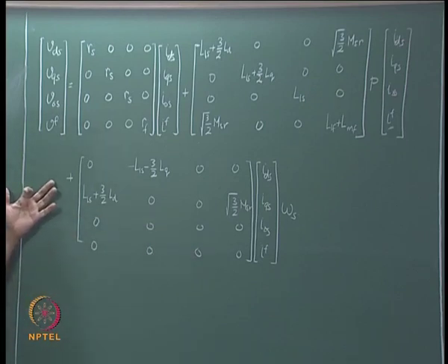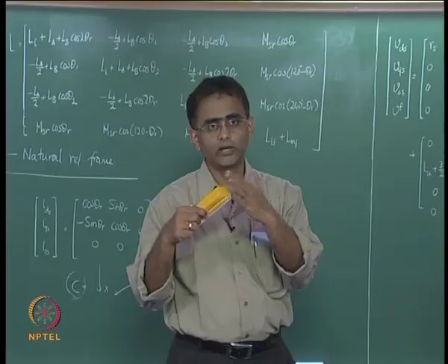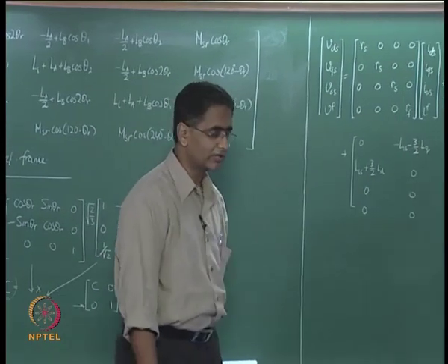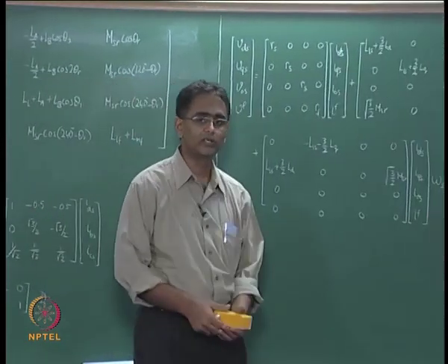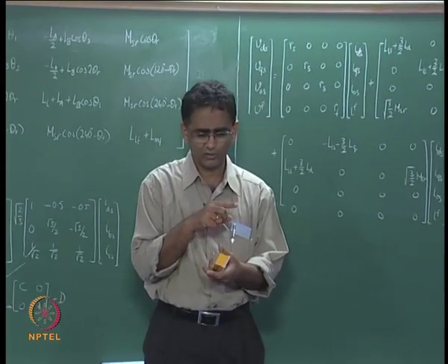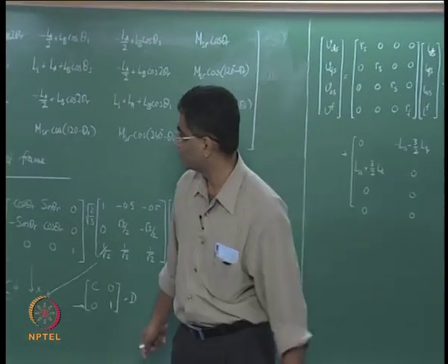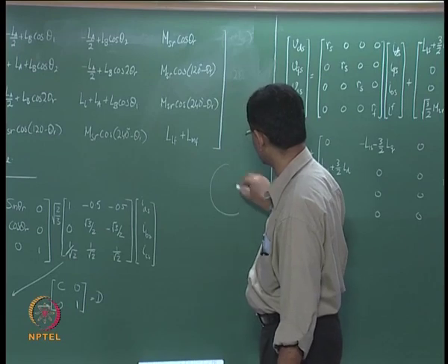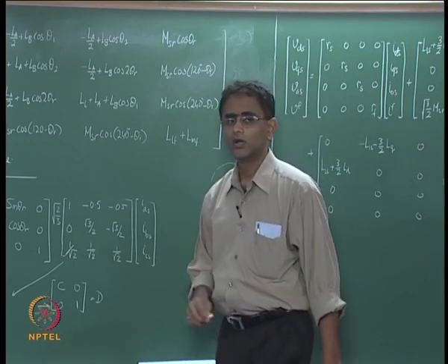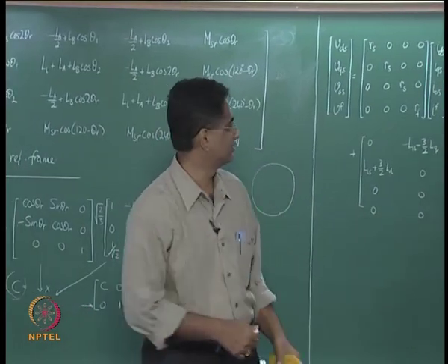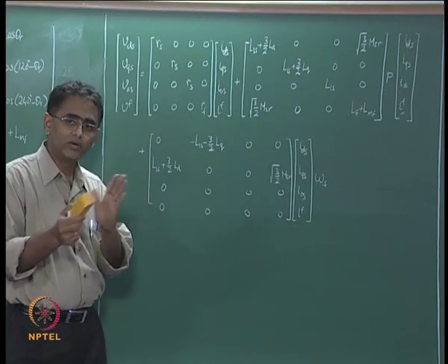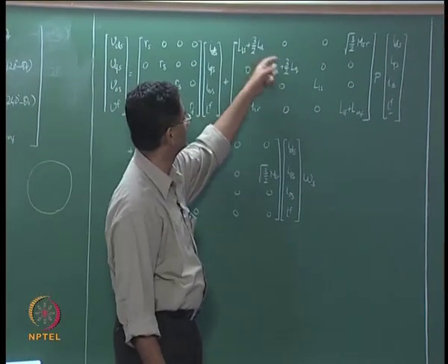So one can extrapolate the arrangement of the equation that we had studied in the induction machine case to this case also. In the case of induction machines we did not have a situation where the surface of the rotor was non-uniform. An induction motor always has a rotor which is cylindrical, and therefore the d axis inductance is equal to the q axis inductance, whereas here we are looking at a case where the d and q axes are different, and therefore these two inductances are different.